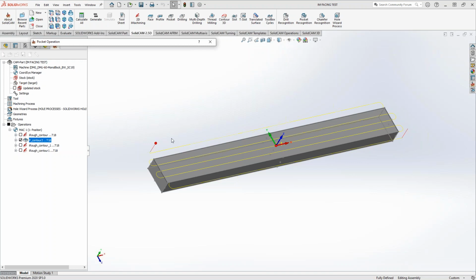Yeah, if we're taking light cuts, just a very skim cut, to be honest with you, a pocket operation is going to be faster for you than doing iMachining. My usual rule of thumb is how many depths of cut. If there's 1, then pocketing is the better one, because all those arc movements, all that island moding, that separation channel for sure, is going to eat up a lot of cycle time. And because it's so little depth, you're not really getting the benefit of the material engagement from iMachining. Whereas if you do it as pocketing, like you see here, that's a very simple toolpath. It's going in the long direction along the length of that part, but that cycle time is much, much less than what you're going to get with just a skim cut of your 2D iMachining.